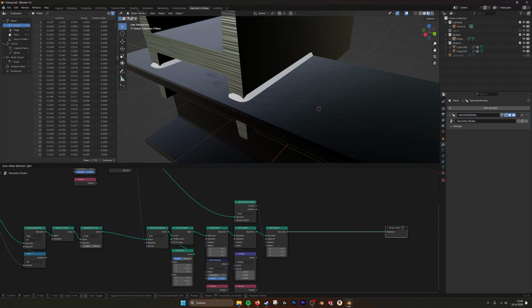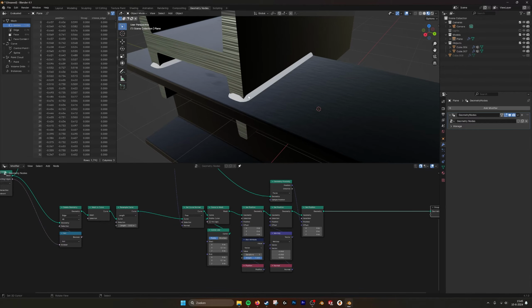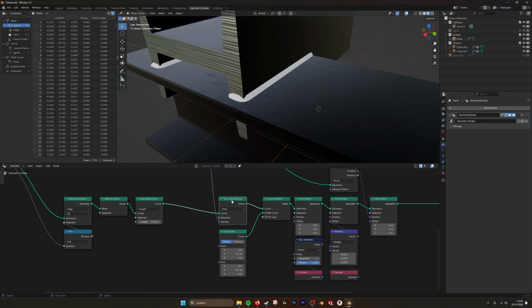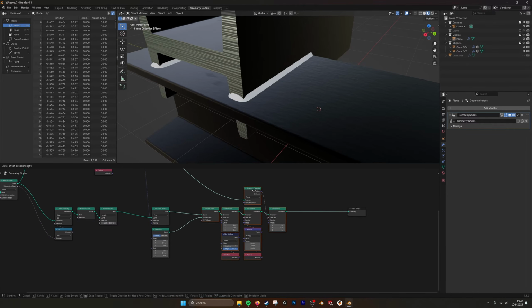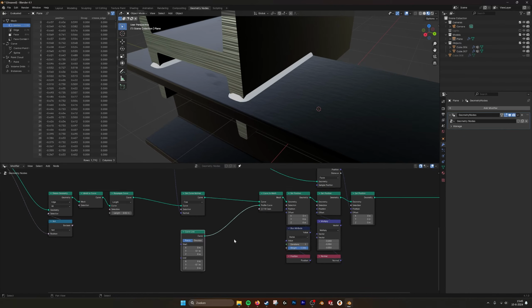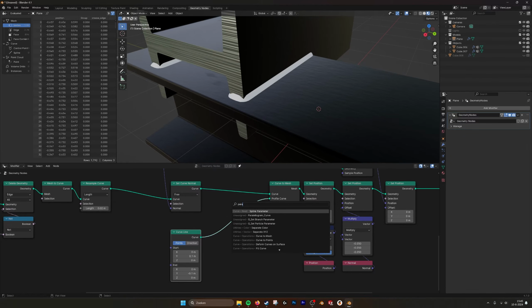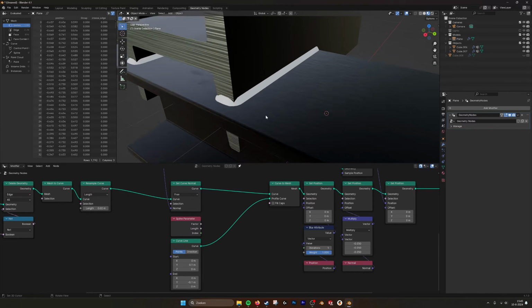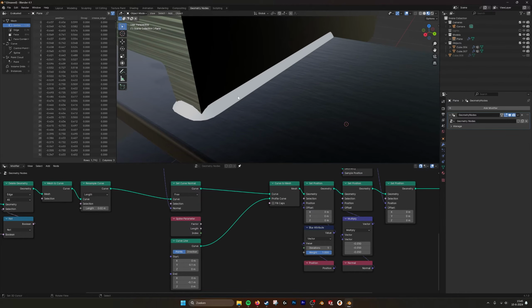Now, this is the part of creating the weld. What we also need is the UVs, so we can map a nice texture over this. And how we do this is we use the curve line and the intersection curve, and we're going to map them to an XY coordinate, and we do that by taking the spline parameter. Spline parameter, when you use the vector, goes from 0 to 1 all the way around, and when you use length, it's just going to accumulate.